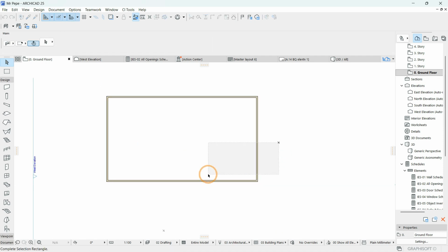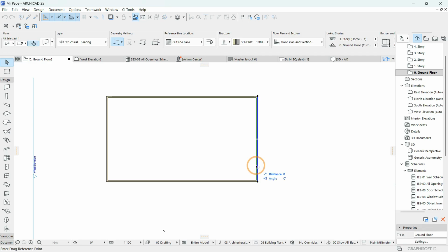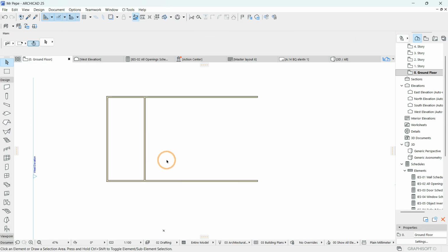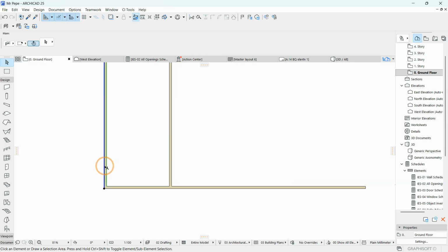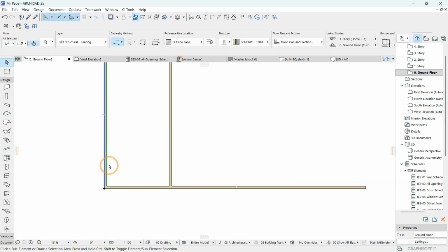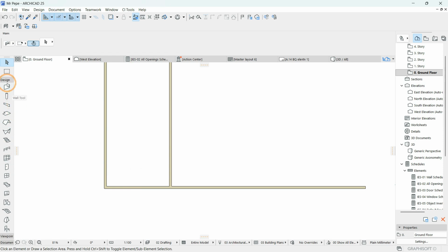I think this floor plan is too wide. I didn't actually draw it to scale, but from now I'm going to be using scale. So let's assume that I have my anteroom here, an anteroom of maybe 2,400. Right. Now let me give you one trick I normally use, and it actually makes my work faster.